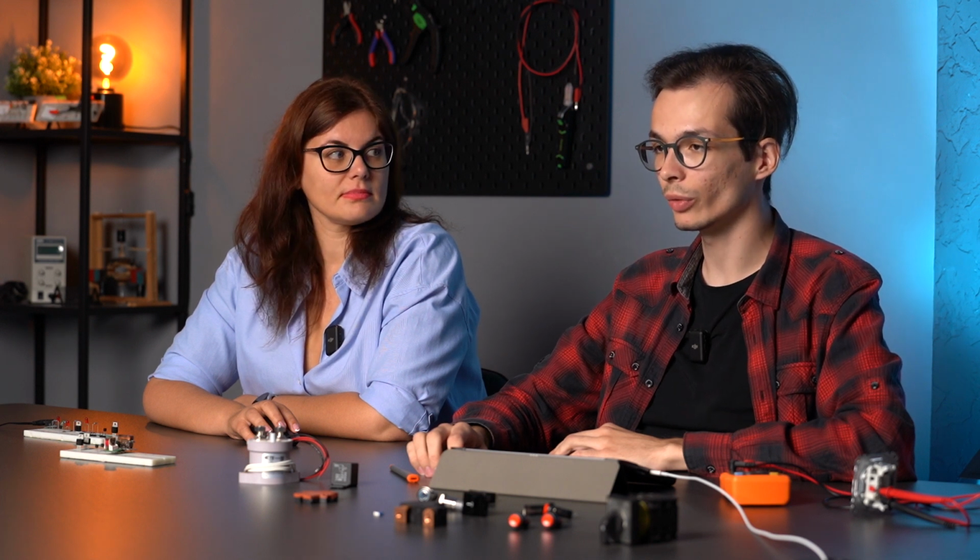For each mechanical switch, care must be taken to ensure that the contacts, when pressed together, first for a very short period of time with an imperceptibly small amplitude to the eye, can start bouncing on each other, and then the state of constant contact is set. This is what we call a bounce, which may cause some circuits to fail.